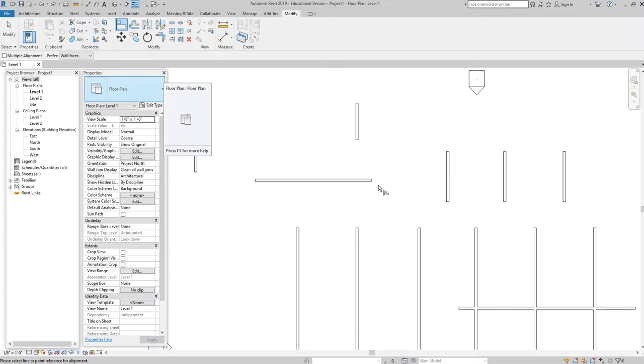I have probably 2 or 3 of them, but this is one of them. I feel like it takes a lot of time. I mean, you have a keyboard shortcut, AL, right? But then you have to go all the way over here to this tiny little checkbox, hopefully get your cursor perfectly on it, check mark it, and then come back over here to create your alignment, right? So it's a little bit of a weird break in your workflow, but it is what it is, I guess.